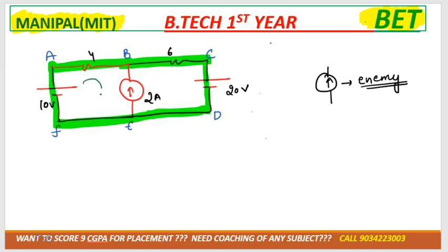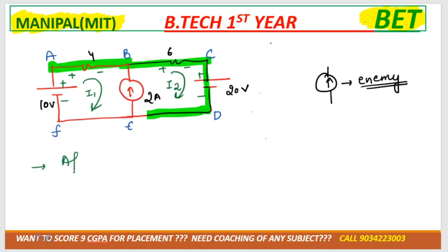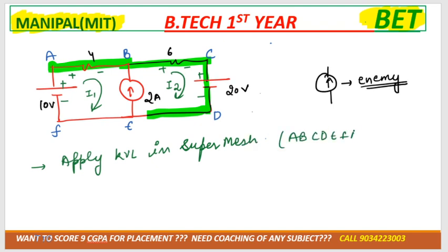Now in this we'll have the same procedure, two meshes, one mesh I1 and another I2. Now mark the sign convention. Never mark the sign convention across the current source, okay? Because basically we can't apply KVL where the current source is present. Simple procedure, right? Now this is technically known as a super mesh, when we are avoiding the current source. Apply KVL in the super mesh. The super mesh is A, B, C, D, E, F, A.